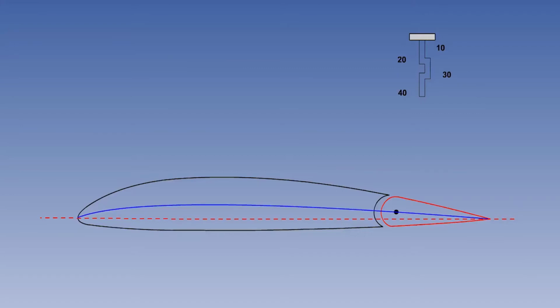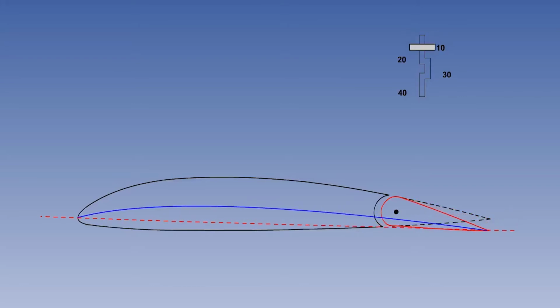We will consider the common types of trailing edge flap first. The plain flap is usually fitted to light aircraft and is of simple construction. The plain flap gives a good increase in CLmax, but with fairly high drag. Here we show a 10-degree flap selection. 10 degrees of flap will be ideal for takeoff, because CLmax will be increased a moderate amount, but drag will increase only slightly.